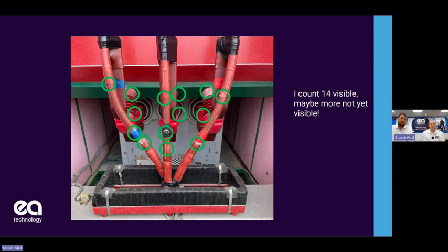So there is activity starting there around the strain relief in the cables, where the stretch relief is. You've got some contamination on the boots themselves. There's some stuff on the bushings at the back. There's phase identification tape been left on. That's always one that causes a change in stress and, again, a breakdown of PD. All very early, all stuff that can be addressed, but plenty of bits of activity on there.